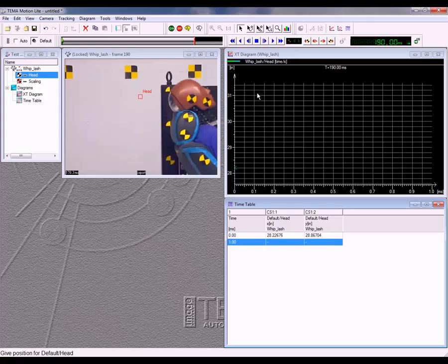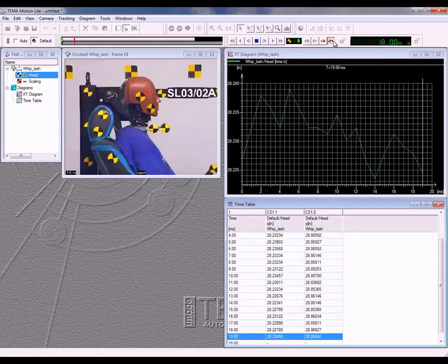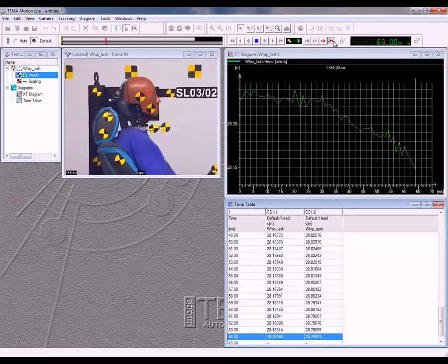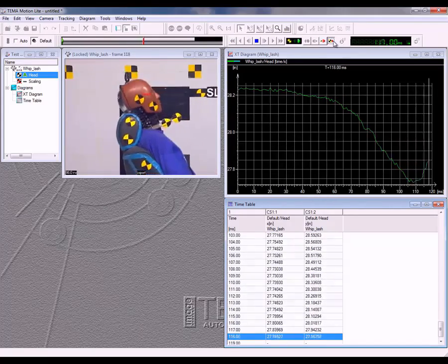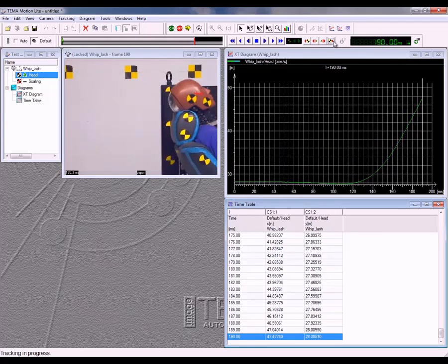Now we can track, and the plot and the spreadsheet will be generated at the same time. While tracking, you should be careful with the setting for each point. On means the point is tracking. Off means there is no tracking and no data will be recorded. In the off position, previously tracked data will not be overwritten. The Z or sleep mode records a sleep position and will overwrite previously tracked data.